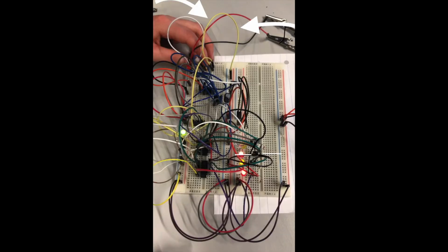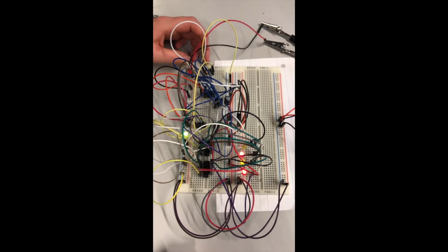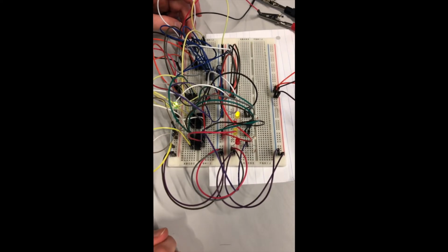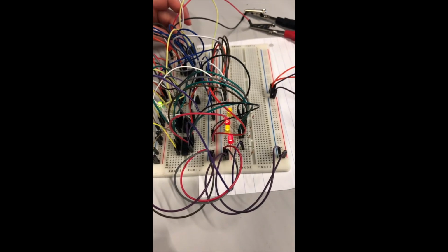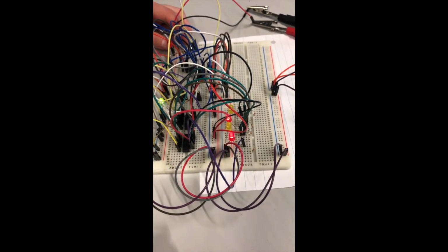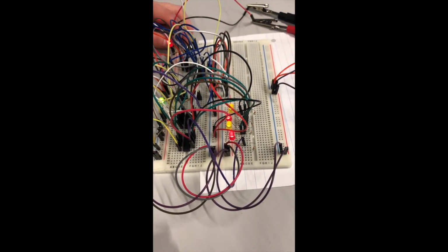Maybe the problem was that we were using a lot of wires and breadboards are very sensitive. But what we think is the most likely reason is that something must have been wrong with the connection in our breadboard. We think this because when moving this yellow wire from the VCC on the left side to the VCC on the right side, we got closer to the correct results. But this is the closest we could get to the right results, even with the help of our teachers. We were also told that we were not the only group that had issues with this exercise.